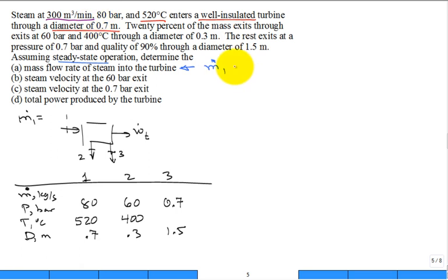And so what we have is the AV, the volumetric flow rate, coming in at 1. And then if I multiplied that by the mass density coming in at 1, wouldn't that give me the mass flow rate? Volume per unit time times mass per unit volume. But a lot of times we're going to pick up the specific volume, the reciprocal of the mass density.